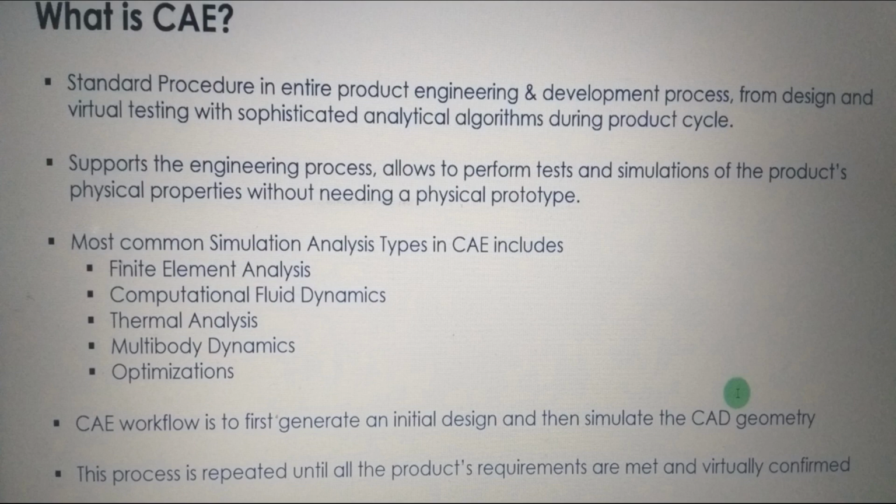And my production engineer says, no, don't use a 2 mm bracket, it's going to be very heavy and it's going to cost us so much. So what is my alternative? I switch back to 1.5 mm and I can change the material. Instead of a standard steel bracket, I can add some composite materials to it, stiffen it on a metallurgy basis, and still make the bracket hold the 10 kg load.